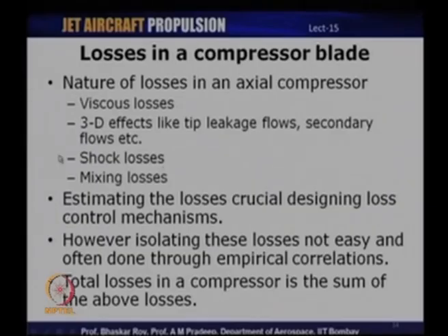The third type of losses could be shock losses, which are true for transonic compressors or those compressors operating very close to Mach 1, at least the relative Mach number. And then the last form or type of losses are mixing losses.